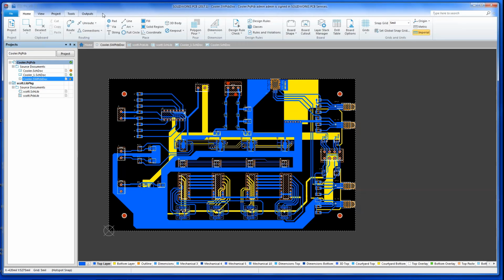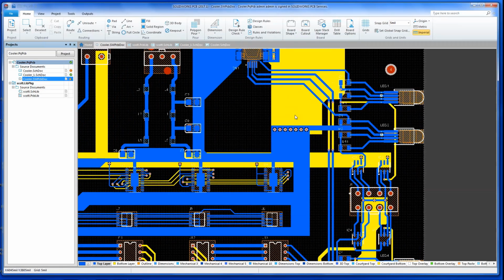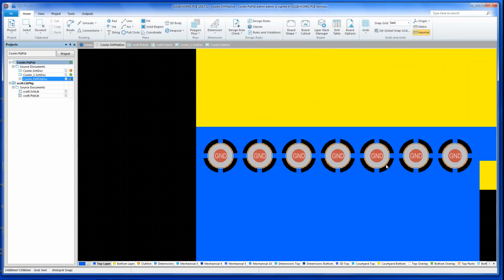So let's take a look at the PCB tools. Again, pretty straightforward. Everything's tab driven, everything's ribbon driven, but the icons very self-explanatory. This design has a lot of the functionality built into it. I've done a lot of copper pour. I've automatically set my thermal ties for my vias and for my components. I can set the clearance. But let's start in the beginning.